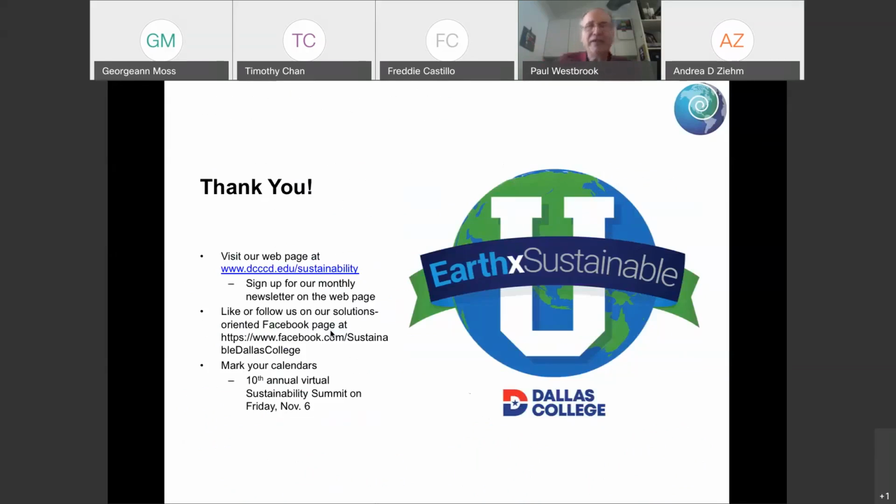So yes, your point is valid. On average, solar panels degrade roughly 0.5% per year. That's quite variable, but that gives you a ballpark. And I've seen that in my own. In my 12 years, I can look at my annual graph and it's sliding down just a little bit. So the beauty of it is I've actually been getting more efficient.